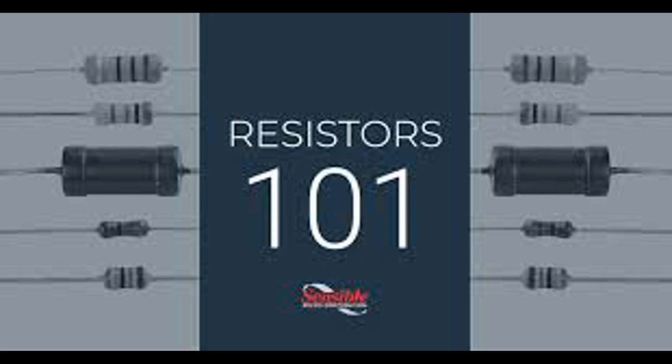Example: If you need to feed a 5V signal into a microcontroller that only tolerates 3.3V, a voltage divider can reduce the 5V signal to 3.3V. Biasing transistors. Purpose: In transistor circuits, voltage dividers are used to set the correct biasing point. Example: The base of a bipolar junction transistor, BJT, is often biased using a voltage divider to ensure that it operates in the correct region, the active region.